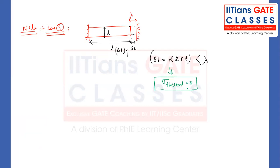The material is freely expanding. The material is not touching the support. The material is saying that, okay, because of the property of the material, my alpha is very, very low. Even though my alpha delta T into L combined together is just 5 mm, you are permitting lambda, suppose 10 mm. For example, we are freely expanding, and when we are freely expanding, nobody is stopping us. If the support would have been here, then we would say that, okay, you cannot expand. But right now you can see that the support is far away from the free expansion case, right? This particular deformation of 5 mm is free expansion.